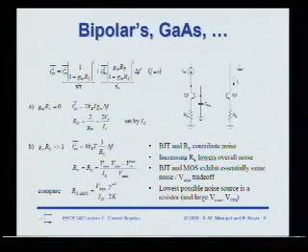How about if I now use a very large value of RE? In the limit, what happens? In the limit, you just get the noise of this resistance. Well, that's good, right? I make that resistance really big, and then I don't get much noise. But what's the penalty again? Headroom, right? Because there's a huge voltage drop across that resistance.